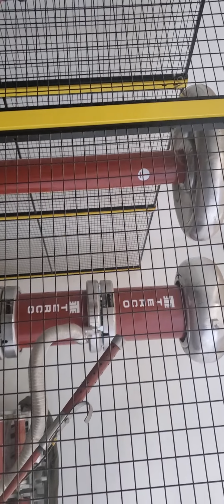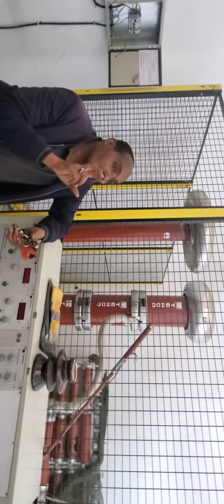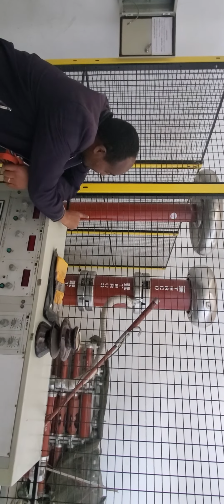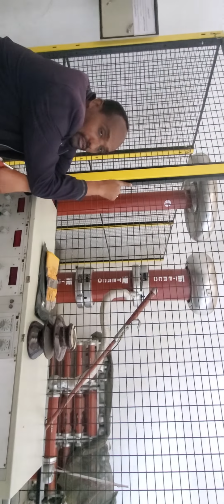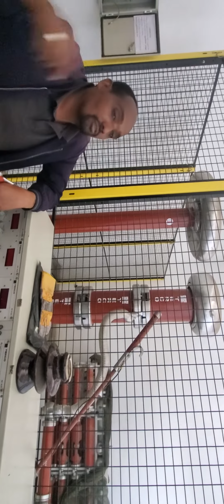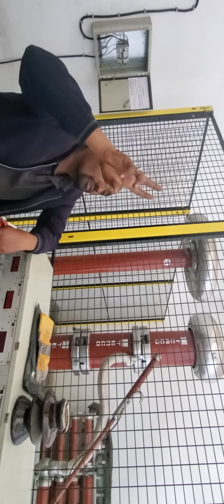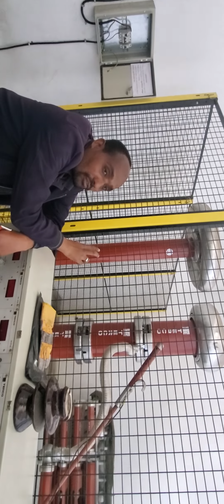If I am connecting 2 voltage sources in series, the output is the sum of the 2, linearly. So here we have 100 kilovolt. The second one 100. The third also what? 100. So the output will become what? 300. So in that lab you have only 100 kilovolt. Here you can have up to 300 kilovolt. So this is the circuit diagram for 3 stage or multi stage.